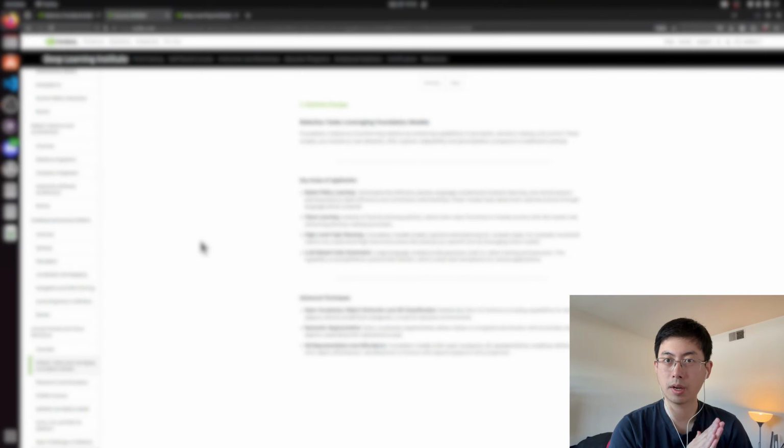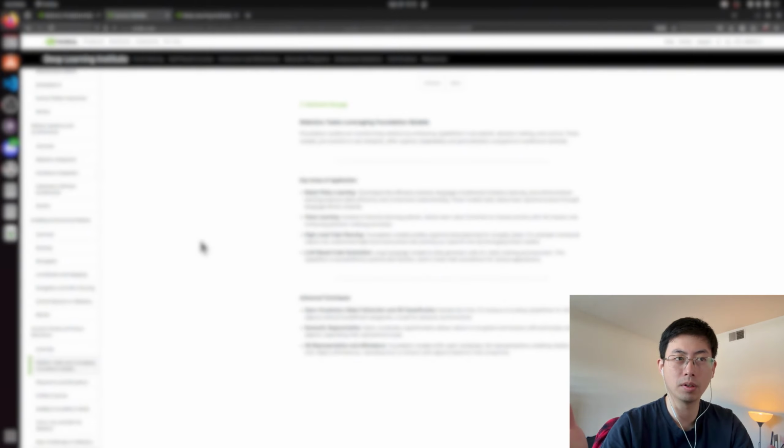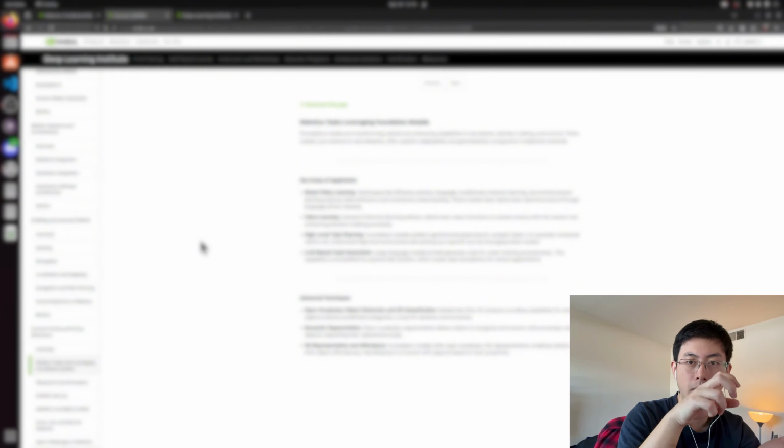All right, on to the current trend in robotics, which is, as you've probably heard, more on AI and reinforcement learning. A key area that NVIDIA pointed out is robot policy learning. So these are different policies. How do you train them to pick up a box without doing more sophisticated control, like you have to pinch this, you have to do this? You just put it into a reinforcement learning model with statistics, and you reward it if it gets closer to the box and even touches the box, and ultimately, with a little hint, it will learn that picking up a box gets the best reward, and that's how your model is trained.